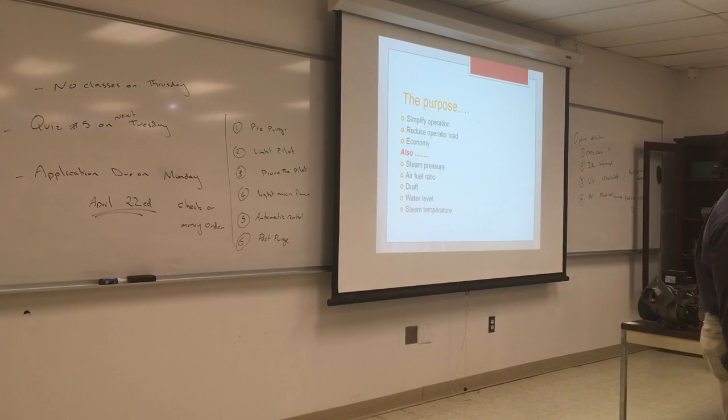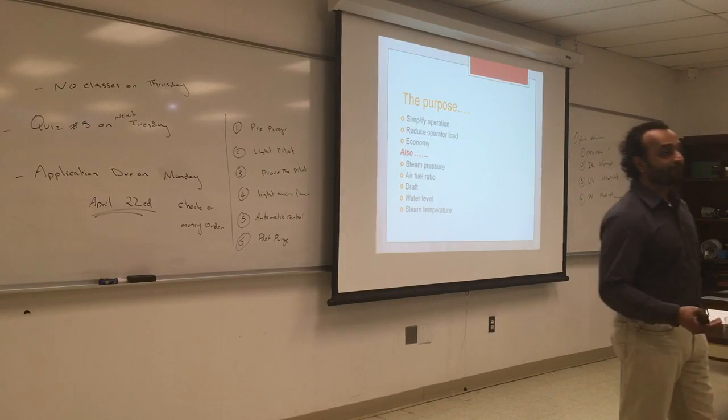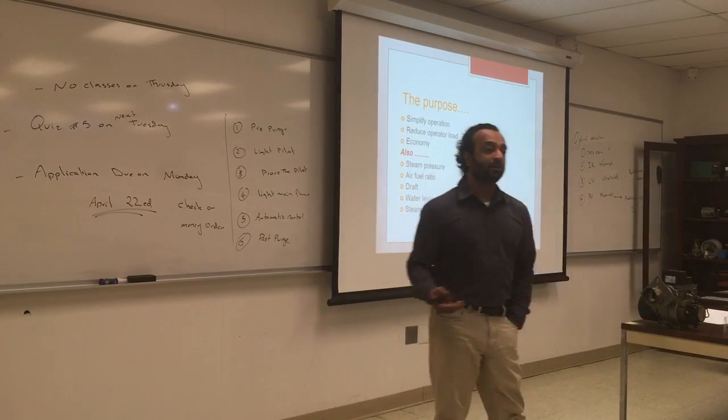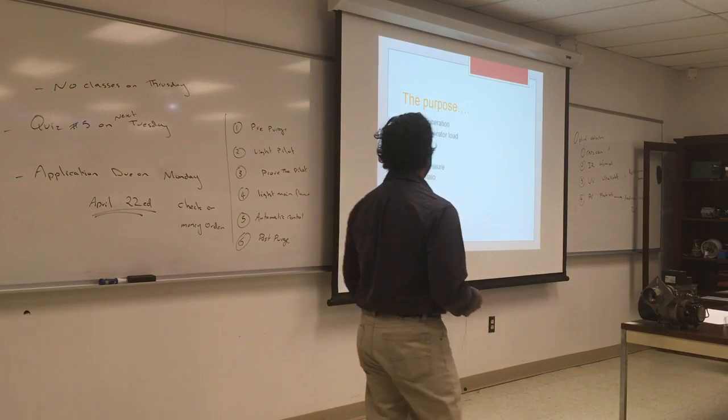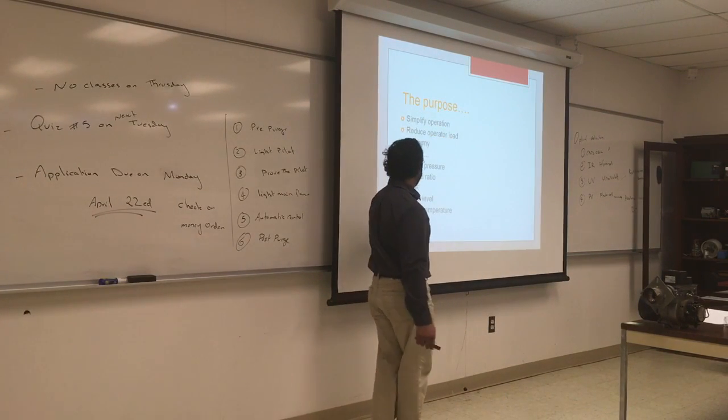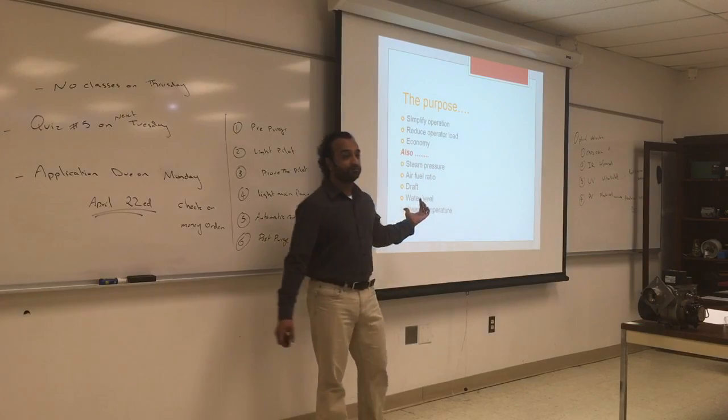Who was here last Thursday? We had one of the steam boilers running low on water, and suddenly the relief valve just deployed. So that's actually good that the relief valve worked. 30 psi was the limit, so probably we reached 30 psi, and luckily the relief valve deployed. So probably that boiler had low water or low circulation. So you always need to monitor the steam pressure and the water level.